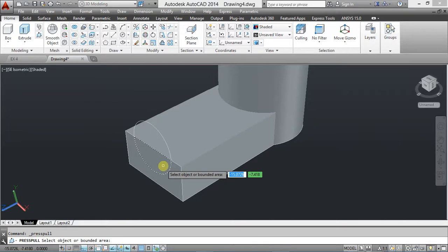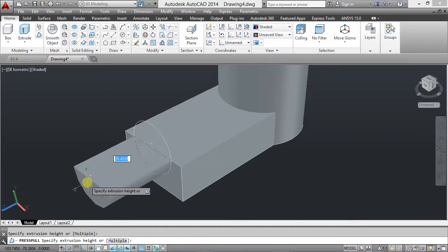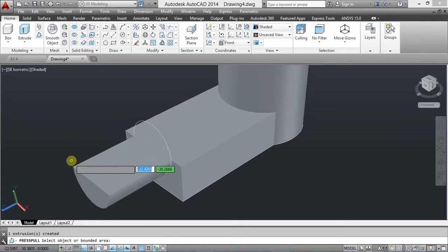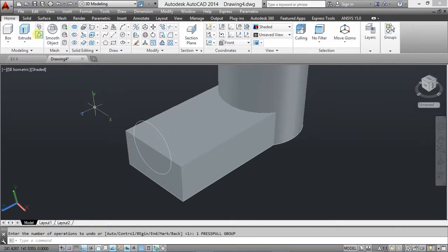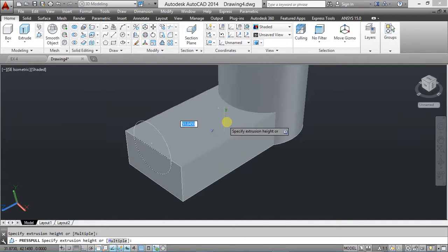Remember the difference between press pull and extrude. Let me show you. If you press pull in the positive direction away from the sketch, it will add a surface like this. If I press pull to this side, it adds a surface to my original sketch model. I'll undo that action. But if I press pull in a negative direction, that is the direction where an object has been,